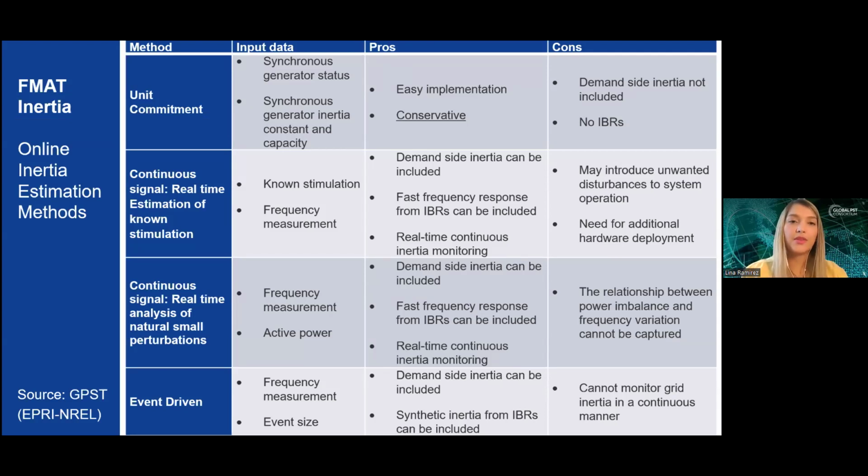Eskom is using that unit commitment approach. We are also studying new ways to provide online inertia estimation, such as using continuous signal, real-time estimation of the ringdown, considering natural small perturbations, and event-driven ways to estimate online inertia.